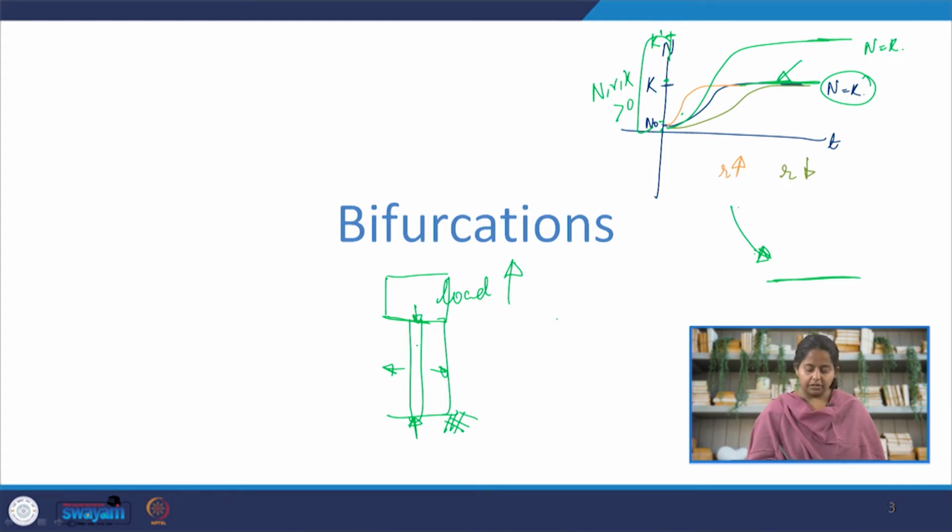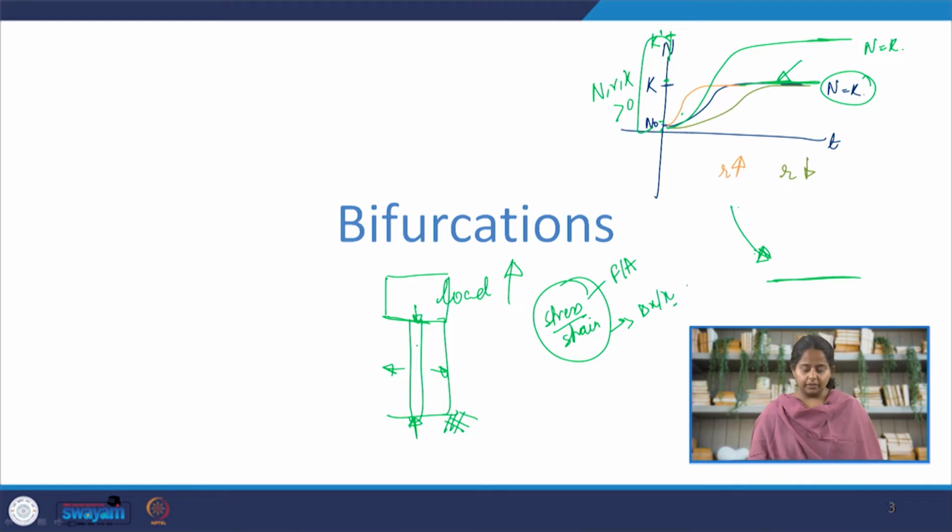Now under compression, there is a particular relationship that we expect between stress and strain. All my civil engineering friends, my strength of materials students who have taken the basic strength of materials course, know what I am talking about here. By the way, stress is force over area, and strain is your displacement over overall length, so basically the percentage of change you can expect in the length of the column. This behavior will no longer be the same once buckling begins.